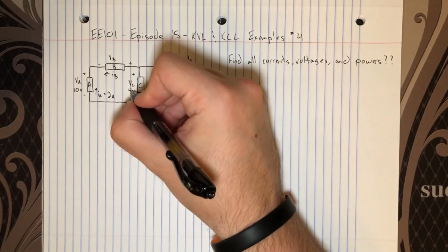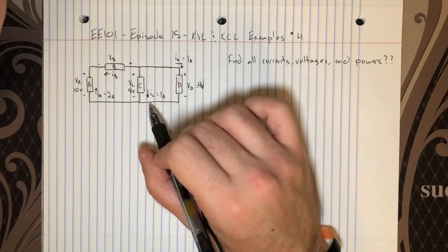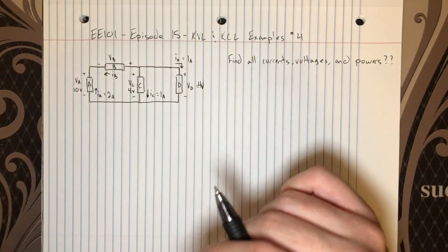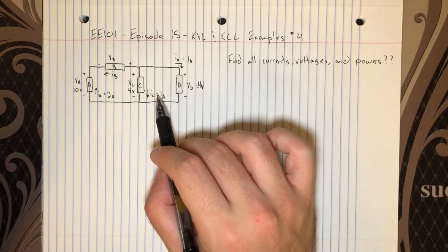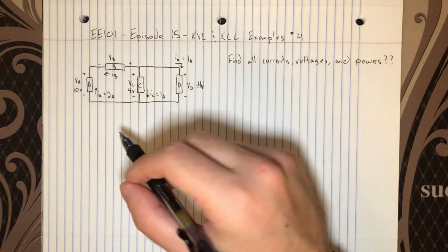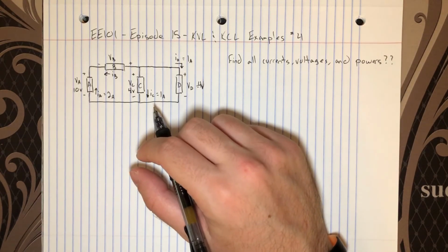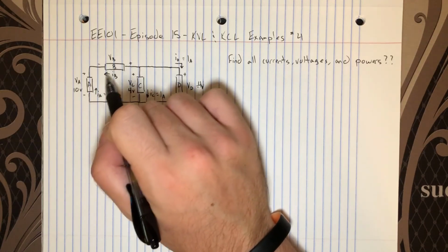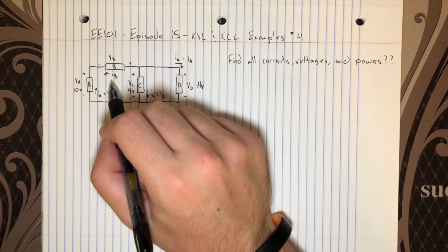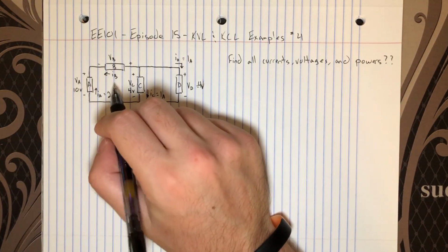When you see a parallel circuit like this, what that really is, is a KVL, but it's just this trivial case where you don't actually have to write anything out. It should be clear instantly. The case of 2 elements in parallel is just as trivial as 2 elements in series. We know that 2 series elements have the same current. And that's a good segue, because look over here at A and B. We have A and B in series, and we know the current IA, which means we automatically know the current IB.